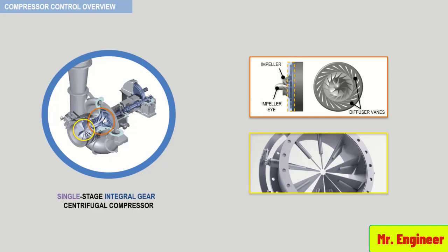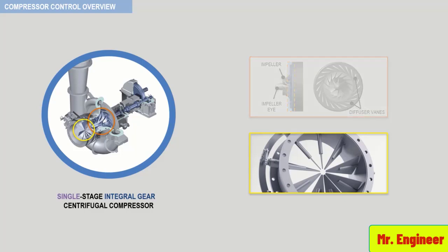Now, before we finish off this video, I would like you to know that adjustable guide vanes, due to mechanical complexity, must be maintained in order to minimize guide vane friction, which can result in lack of guide vane movement. I strongly advise you to consider purchasing the guide vane actuator and control arm assemblies. This is done to minimize the possibility of excessive assembly friction. Remember, the guide vane assembly is a system and must be treated as such.